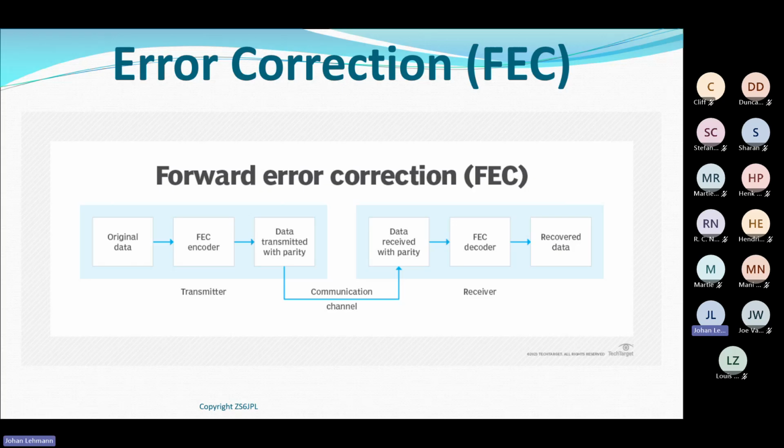If the data is not correct, and this is now where things start getting complicated. So all the CRC does, the CRC tells me that all the information that left the transmitter, all that information arrived correctly at the receive side. That's what my checksum, my CRC tells me. Whatever's left the transmitter has arrived on the receive side.